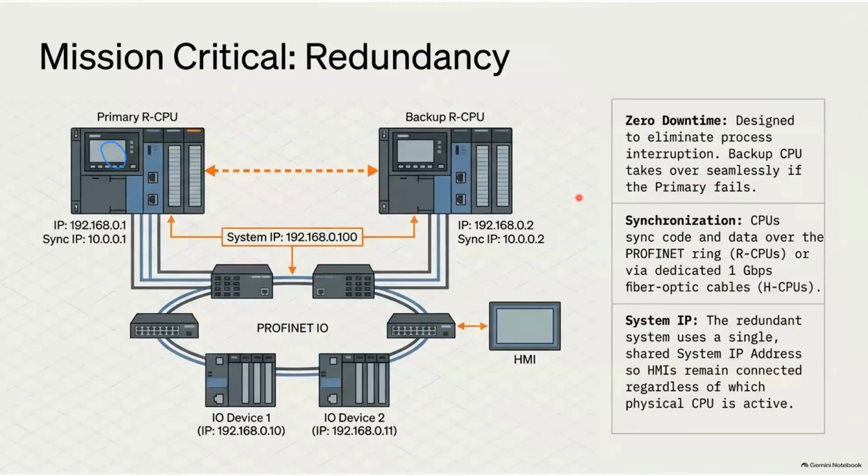Good. This is redundancy. Redundancy is for distributed control systems, for any plants that operate 24/7. If there is any problem with a single module, and we have to turn it off and reset it or perform any upgrades, then we need a backup. We need an alternate, similar system. That is what the redundancy system is.